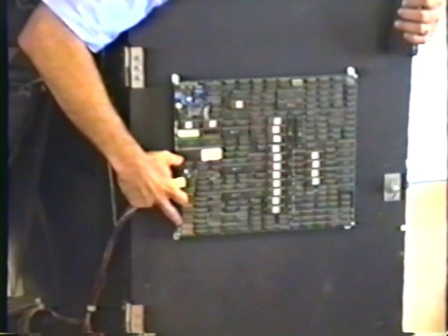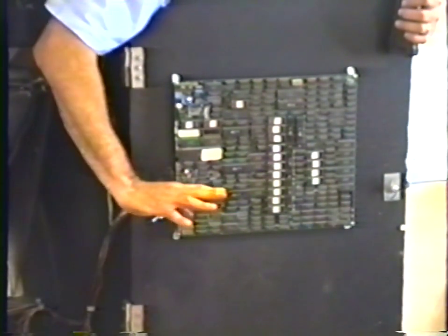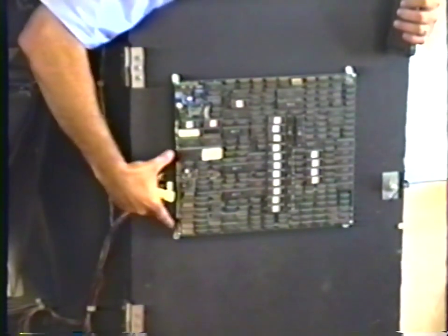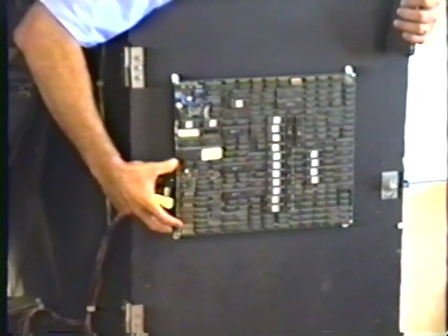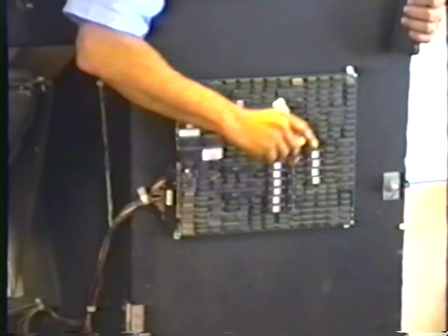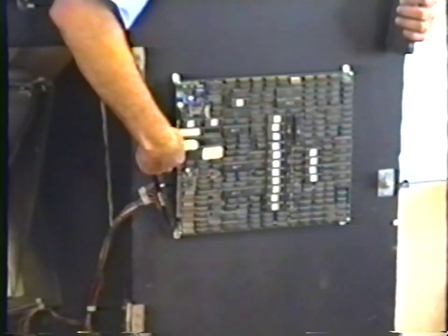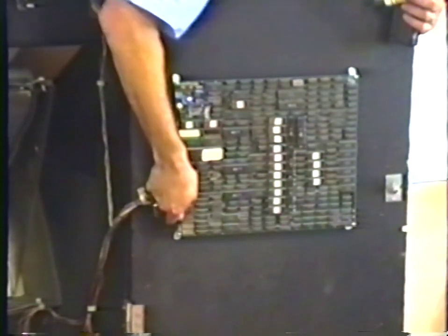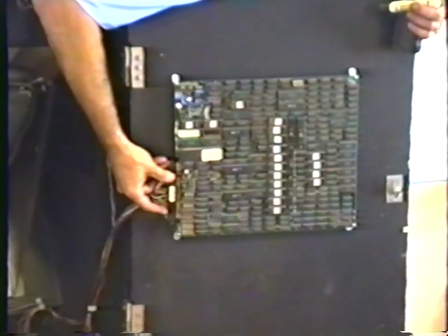So before you adjust the power supply, I do this all the time. At the very least, with the power turned off, because you never plug in anything or unplug it with the power on, other than the AC power cord, obviously, you might try plugging and unplugging this a couple of times. That's something you should always do anyway, because just the process of plugging and unplugging it cleans it off and makes a better connection. But it's best to clean this card edge off with a pencil eraser or even a dollar bill. Just take a folded up dollar bill and rub it against the connector, and it cleans it right off. That's pretty important because you don't want to have any dirt at all on the connector.